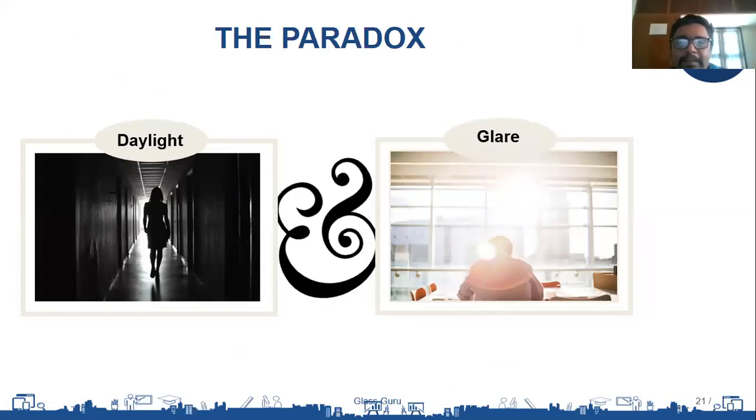So it all depends on what is called our visual comfort. Our visual comfort depends on our eye, where we are sitting, and the light source that is there. And if the light source is going to be your facade, if the contrast ratio goes beyond, as a thumb rule, 1:10, you start feeling some visual discomfort. So that is what we call glare. To avoid this, you will have to choose the glass depending on the window to wall ratio, and VLT becomes a very important factor over here.